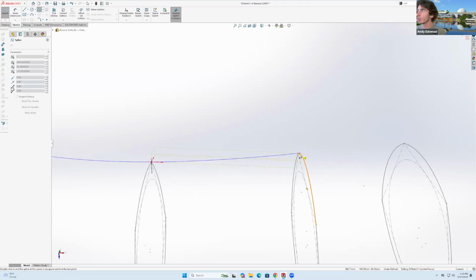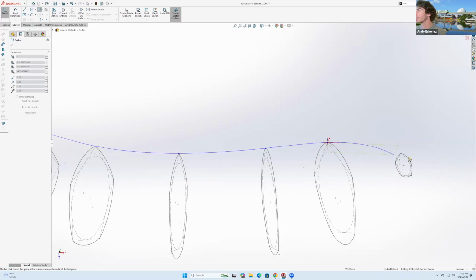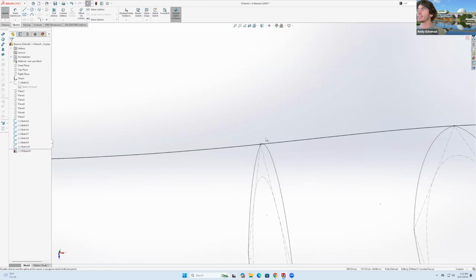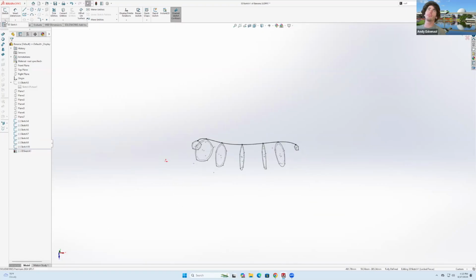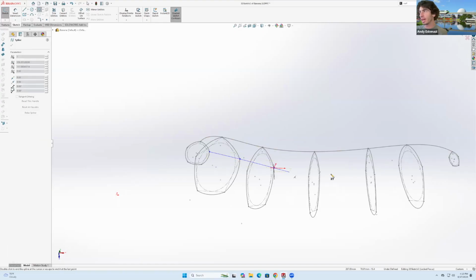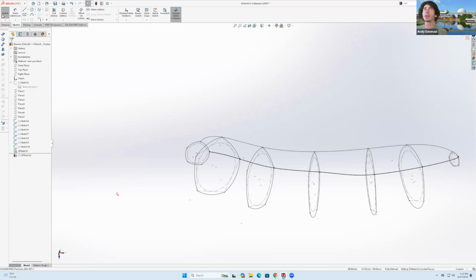Right there. And I click escape. Very good. I think yes. So now once you've done that one, to exit a 3D spline, you click again on 3D sketch, then you click escape, and then I'm gonna draw another. So we're gonna draw 5 of these. Make sure that these are different sketches, otherwise the technique is not gonna work. There we go. Click then escape, and then there we go.